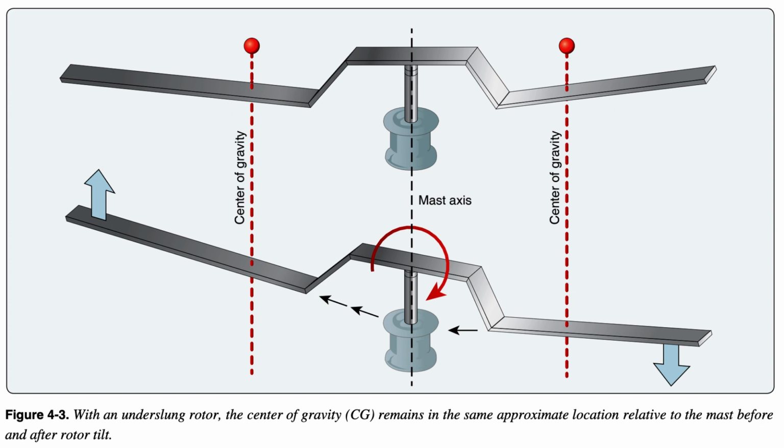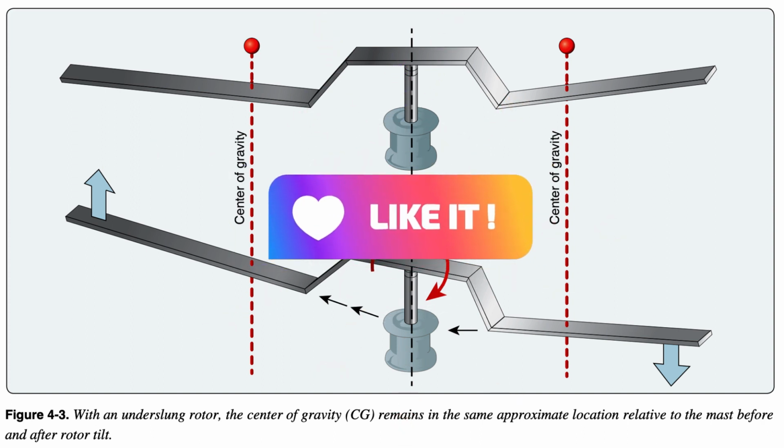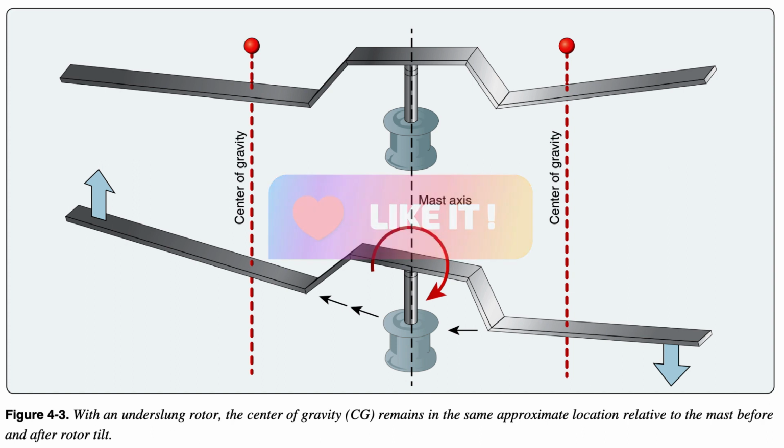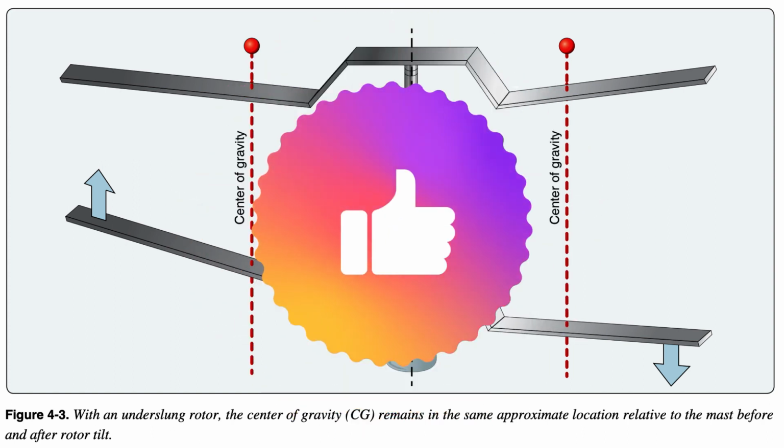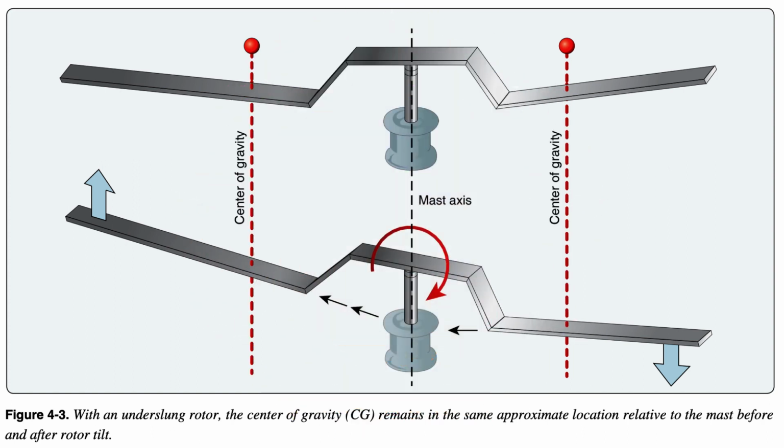Each rotor system design has a maximum flapping angle. If flapping exceeds the design value, the static stop will contact the mast. The static stop is a component of the main rotor providing limited movement of strap fittings and a contoured surface between the mast and hub.